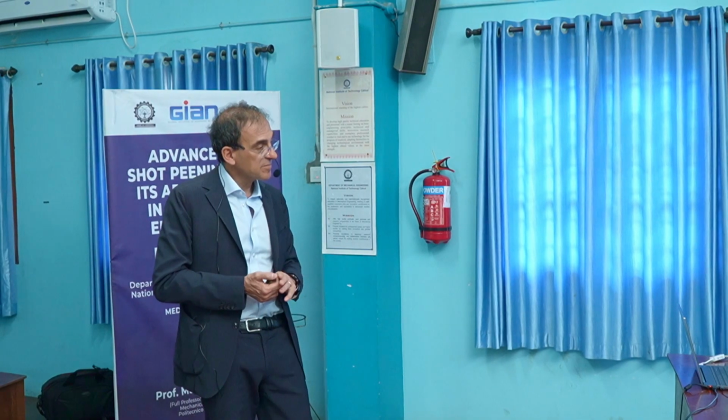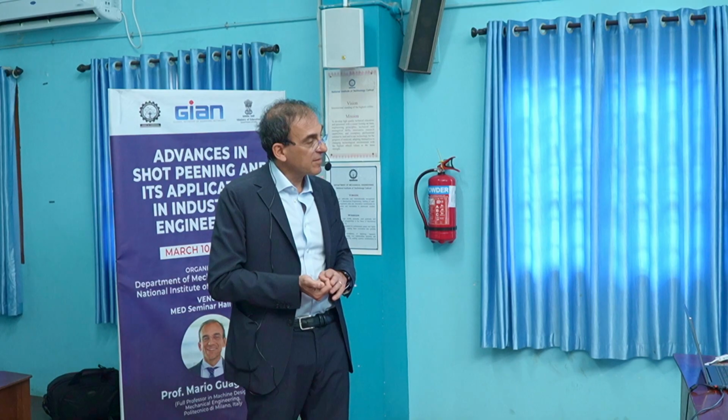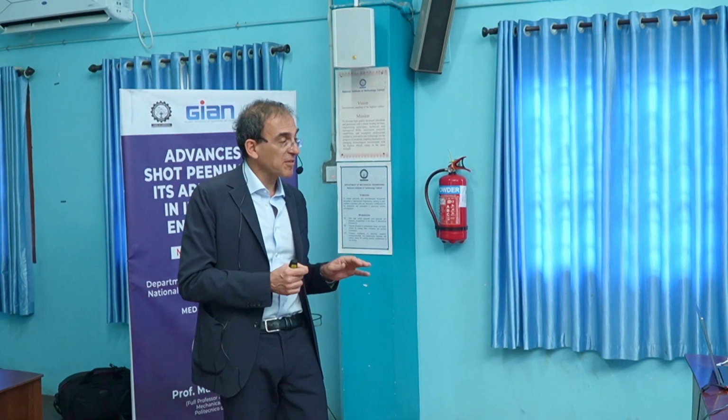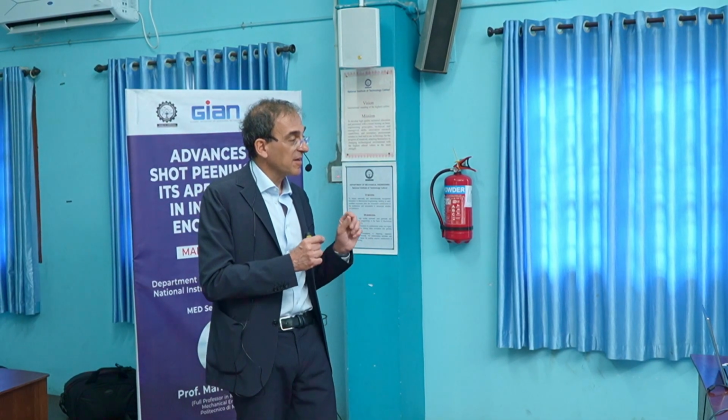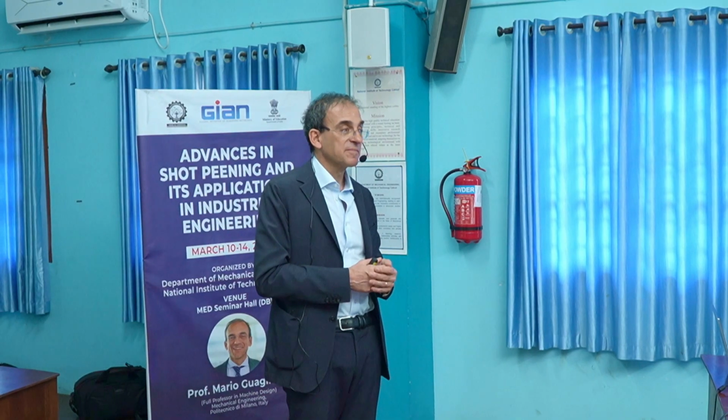It is not influential on fatigue strain, let's say. So will it affect the residual stress in such cases, if it is not plastically deforming the microstructure? If you want residual stress, we must have deformation, plastic deformation, some plastic deformation, otherwise we cannot have it. Okay, thank you.